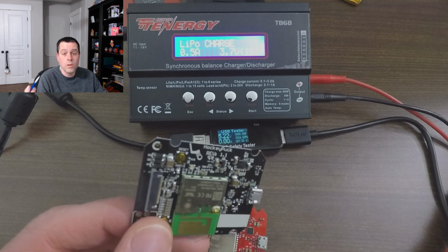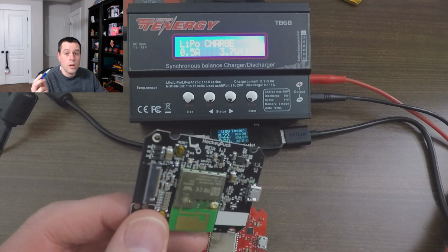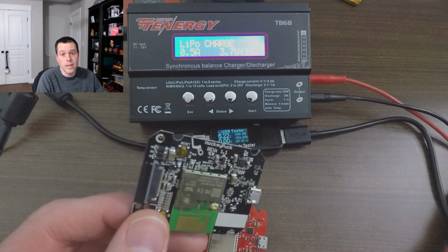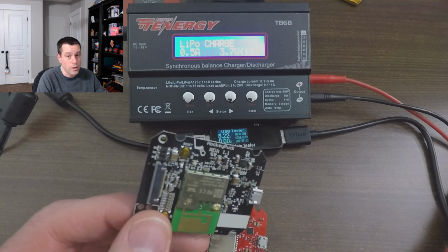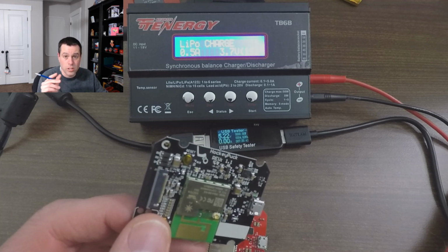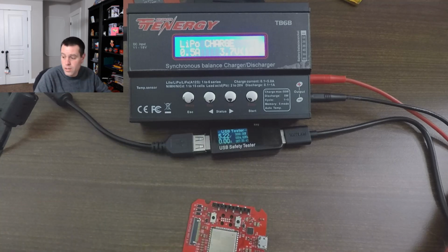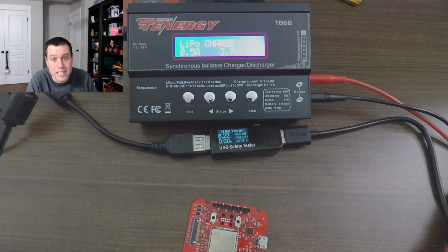And so you can even do things like that where it's like, I'm not sure, just put the footprint in the design and then add it later. And you can do the same thing with little jumper pads. You can just have two little solder pads right next to each other that aren't connected. And then if you want to enable that feature, you just put a little blob of solder across it. Hugely helpful, and it saves you from having to send another board off to be fabbed and assembled.